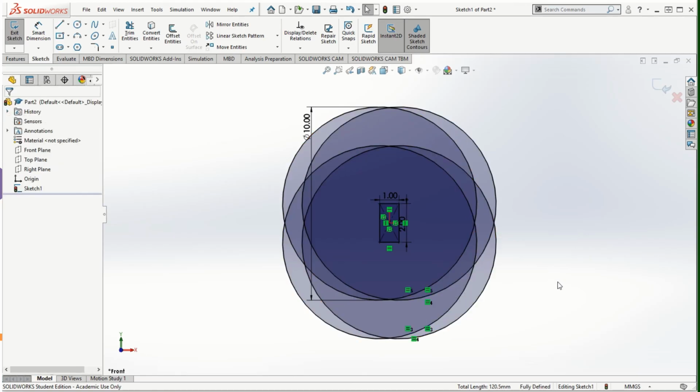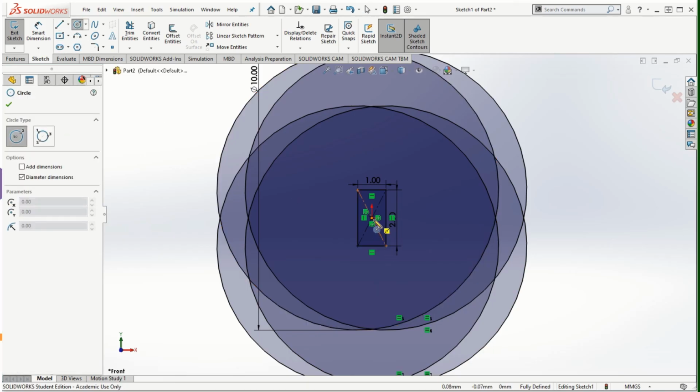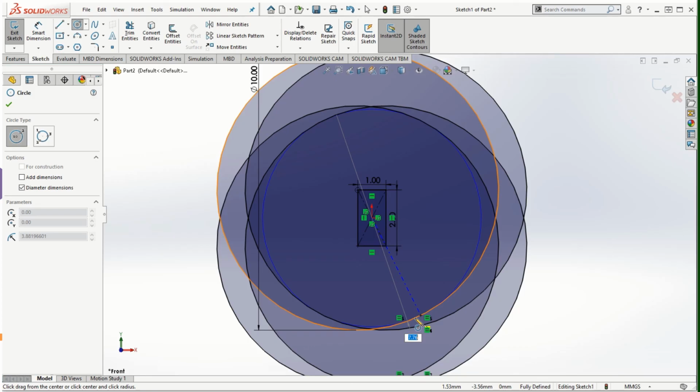Once we create the possible locations of the holes with the minimum hole diameter of 10 units from the extreme corners of this rectangular tolerance zone, I will create another circle by looking at the maximum possible diameter of the circle that will be common to all the 4 circles.